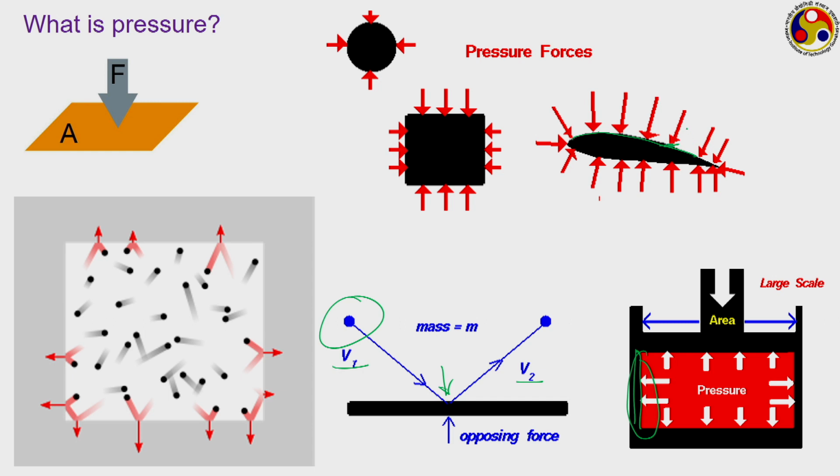Like if we pick up this particular point, this is the direction of the force, whereas if we pick up this particular portion of the surface, the direction is this particular one. So, depending on the orientation, the direction of the pressure force will also keep on changing, and that is why while evaluating the magnitude of this pressure, we have to be very careful about which area we are talking about.